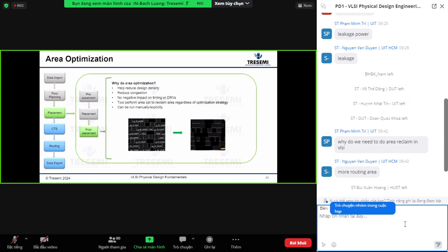So it is both active areas. When active areas are lower, that means leakage power is lower. Leakage power is really proportional to your active areas, meaning gate areas and source drain areas. So leakage power absolutely is going to be lower. That means you meet timing and you have lower power consumption. That's why you want both timing and power. So your chip will consume less, your battery will last longer, right?